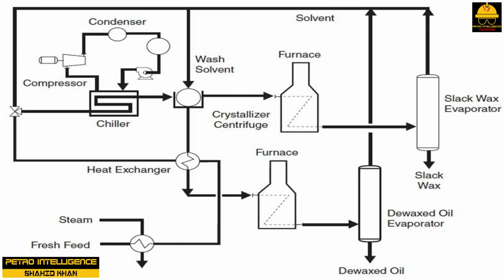1. The oil is mixed with the solvent and cooled. 2. The oil is filtered and the wax removed. 3. The solvents are recovered and recycled. This picture shows a typical solvent dewaxing process.